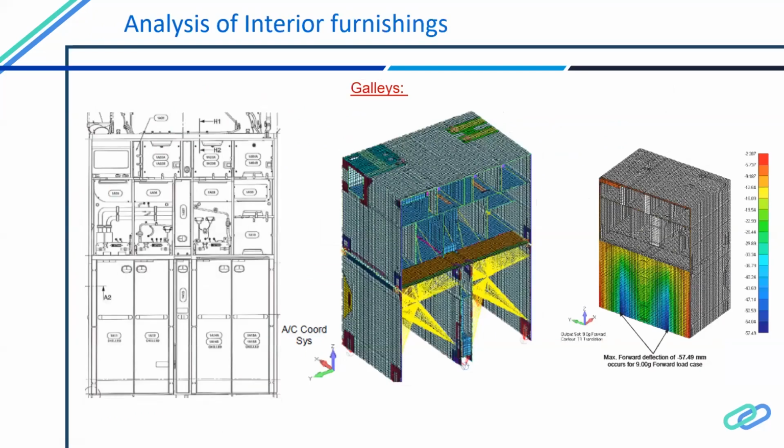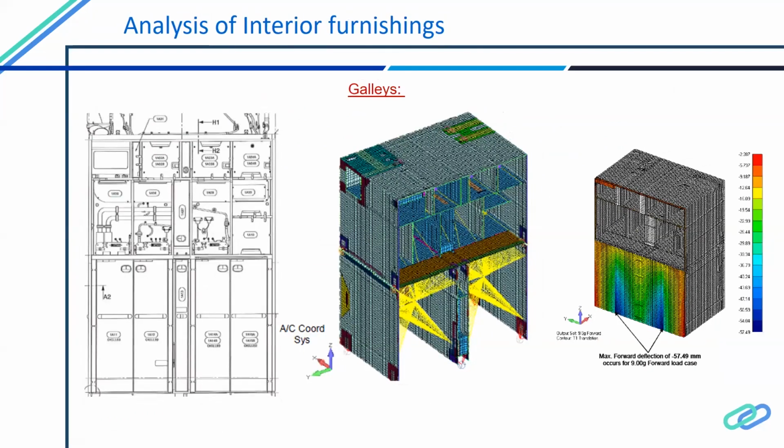Yeah, and here I've just included the finite element model and the deflection that we have predicted for one of the galleys. This particular slide just shows an overview of how we have built the finite element model, taking into account all structural panels of a galley, and then taking into consideration all compartment loads and trolley loads and all other things.